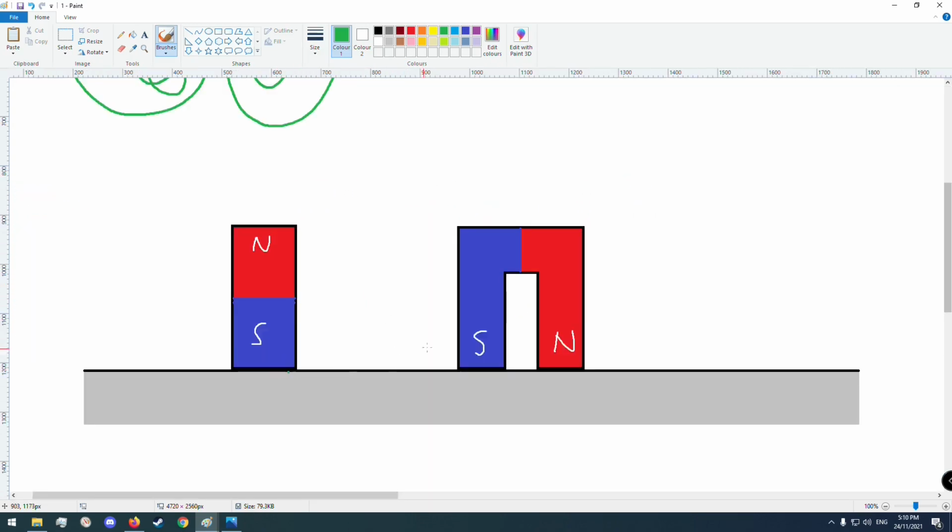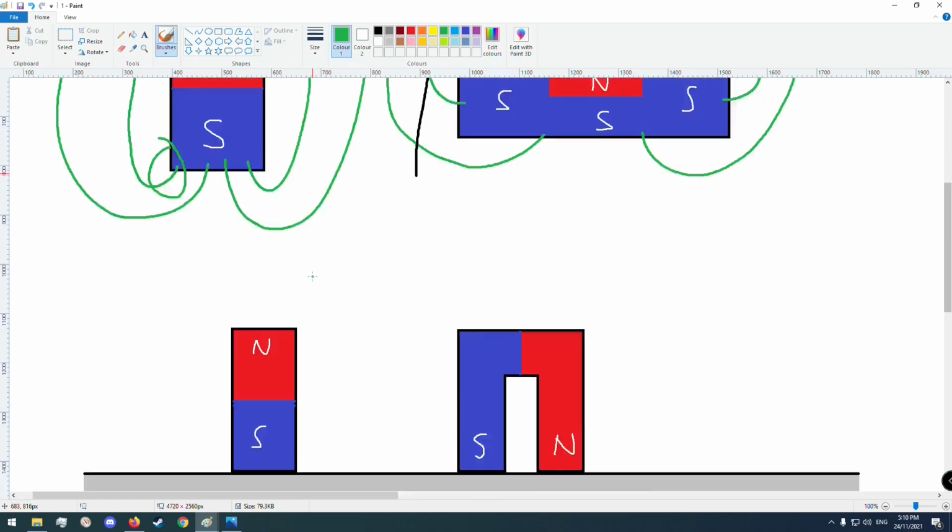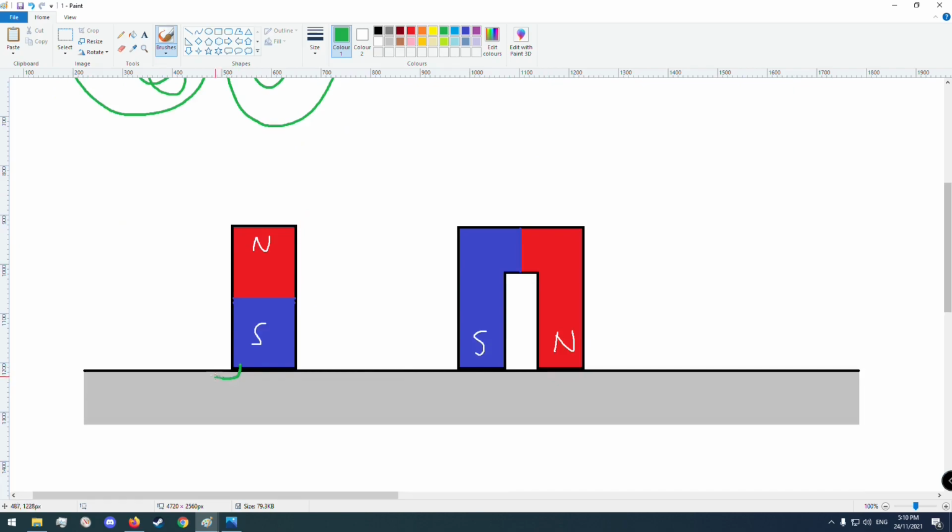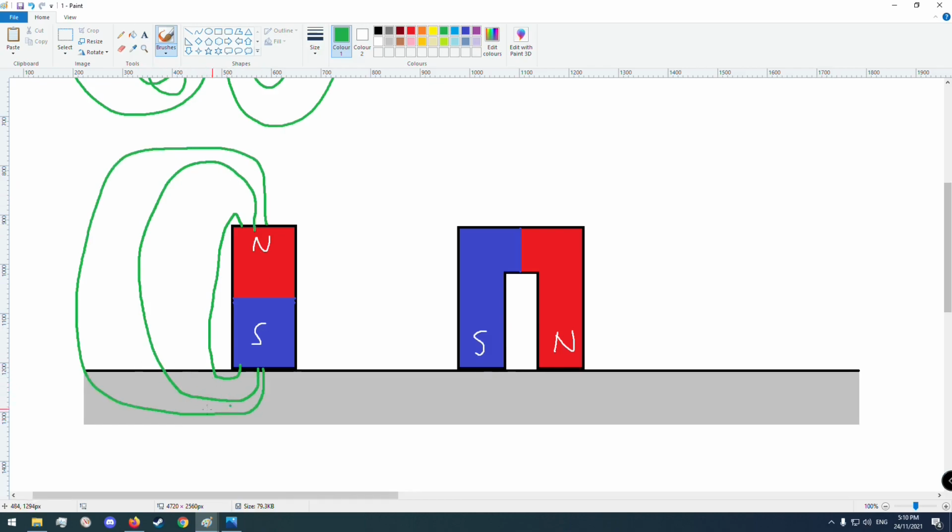Magnetic field lines also like to go through usually ferrous materials. So instead of it just going out into the air like this, what will happen is it'll actually stay very tightly through this material here before spreading out. It always remains within this region here, but up the top you can see it arcs out a lot higher. Also, in a case like this, for example a horseshoe magnet, it would go straight from south to north, just like this, and you wouldn't have many extraneous fields around it. So this is why horseshoe magnets are very strong.